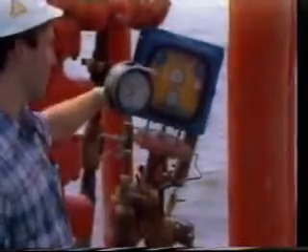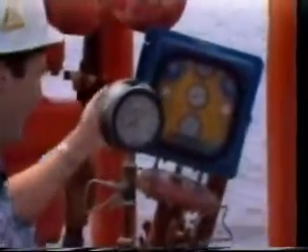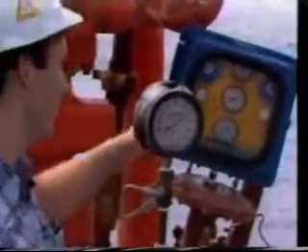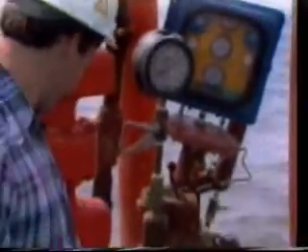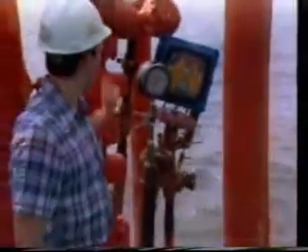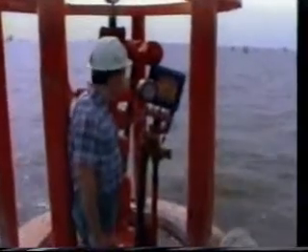You have a low and a high pressure setting. When it reaches the low pressure setting, it needs to get more gas. It'll sense that and open the valve. You'll get an increase in casing pressure until you reach your high level. The high level will shut it off, and the valve will close. You've injected gas in the annulus, and you'll see a rise in the tubing pressure as you start to produce fluid out the flow line in the back.